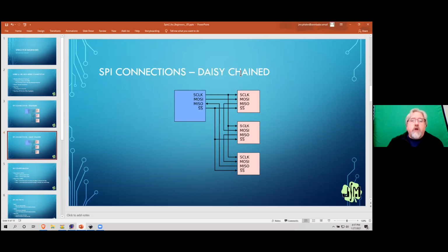With a little bit of coding, I was able to write an assembly cog that could run very fast, since SPI is fast anyway, and do low frequency PWM over those 32 outputs.